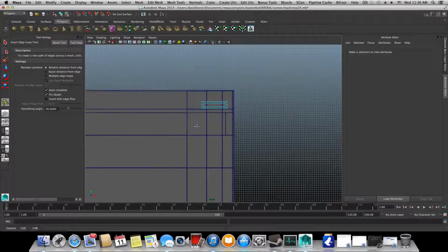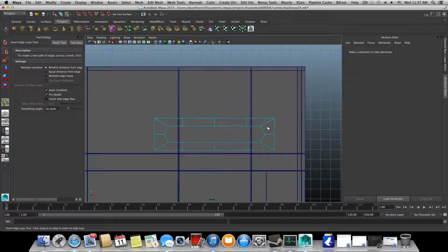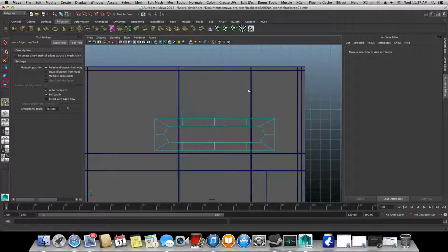Okay, now by luck the front view really shows me both of them, so it's easy. If for some reason you started your whole model in a different way, then you will have to do your own modification with the camera in order to set this correctly. But you can always use the X-ray, so no matter what angle you started your model with, you will find a way to see both of them and set those edges accordingly.